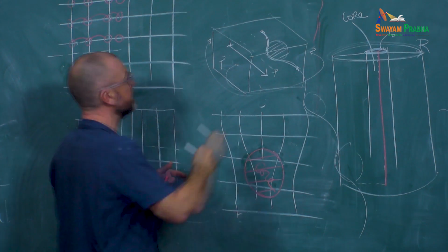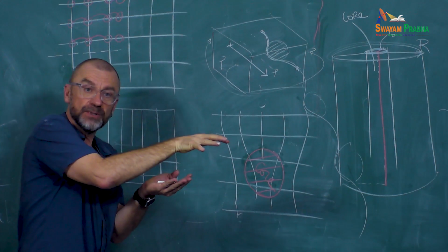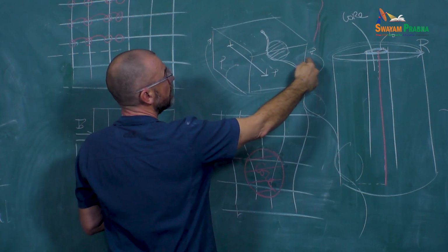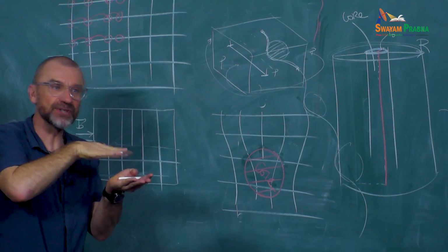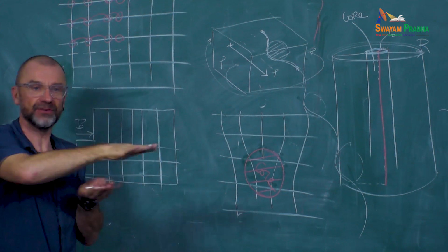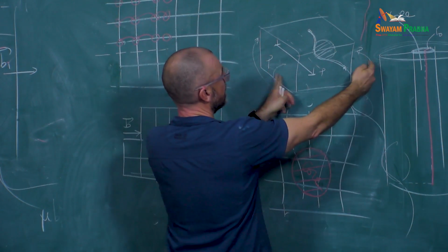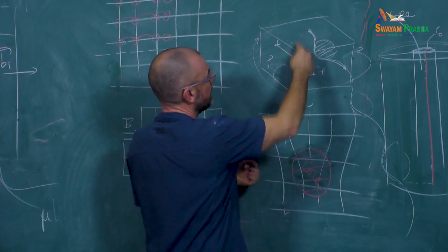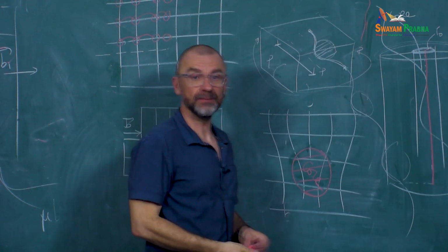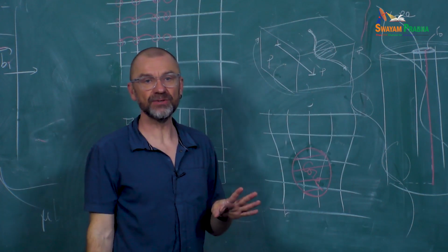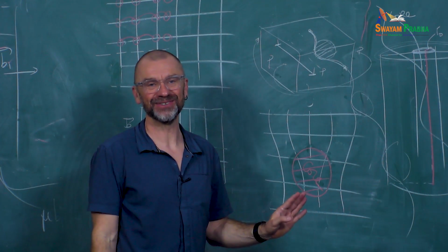Infinite but periodic. So it means that in your simulation, for example, if it's a precipitate, the dislocation goes through, it's going to shear the precipitate. Then it's going to go here, it's going to come back, and then it can shear the precipitate again, and so induce a double step, then a third step, etc. So the artifacts are coming mostly from the periodicity in this direction here. Because ahead of this dislocation, there's another dislocation doing the same. And so you have two parallel dislocations with the same Burgers vector. That's the worst case scenario for interactions.